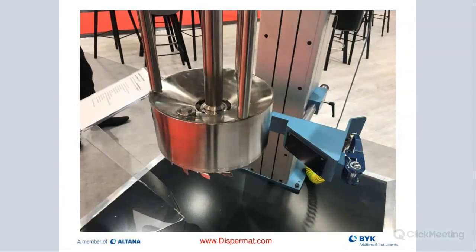That's an example of a production scale basket mill. Up here, we have a bead filling port, and you can see the cooling rod right here. It's also a stabilizer rod. On the back here, we have the cooling fluid out. And behind here, there's a third rod that measures the temperature. The great thing is we're able to measure the exact temperature of the mill base inside the basket mill, where we have the highest energy input and see the highest temperature rise during the process.